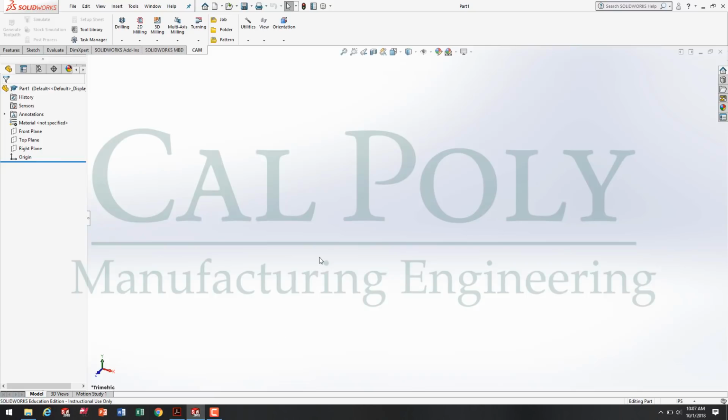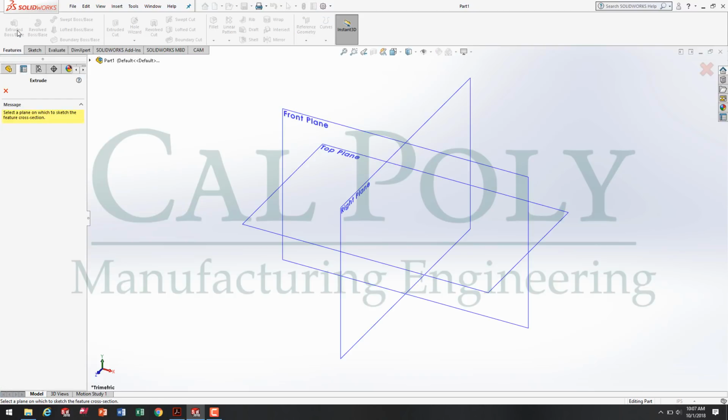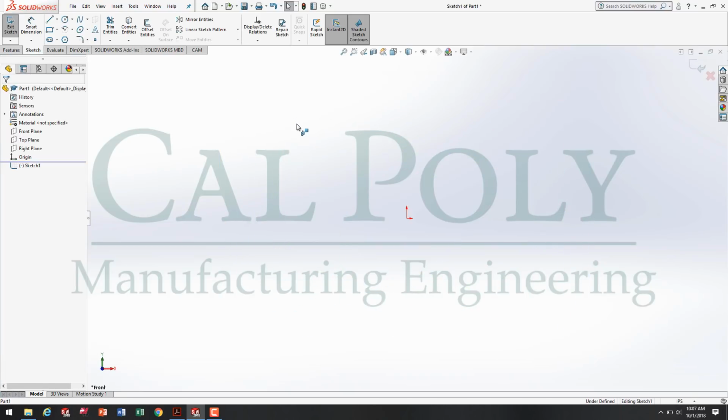So to do this, we're going to use the Features menu up here and the Extrude tool. So we're going to click on Extrude. We're then going to select the front plane. From this point, we need to draw a rectangle. All of our sketch tools become active up here once we select the Extrude feature and select the plane.